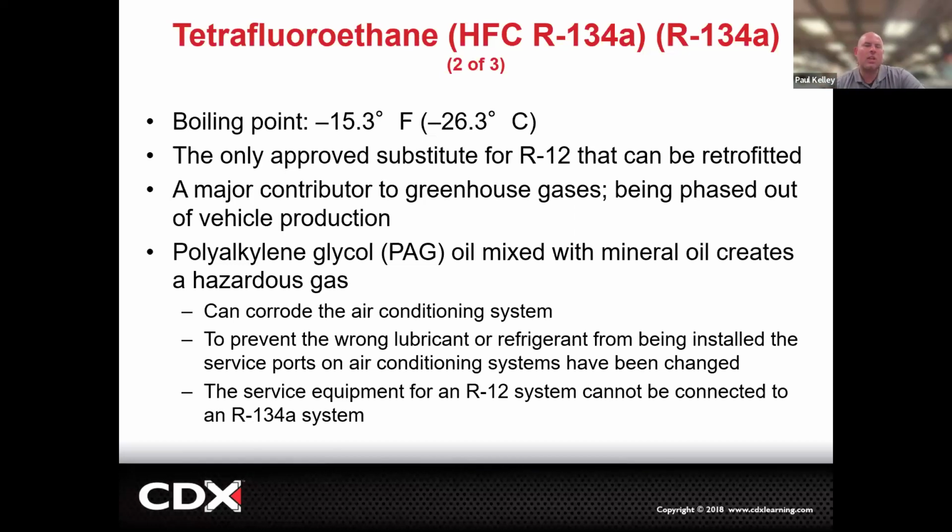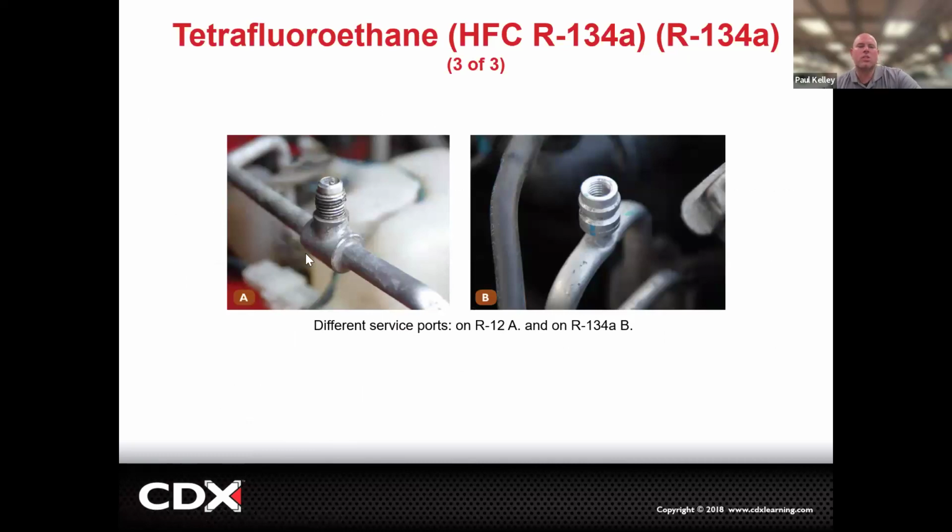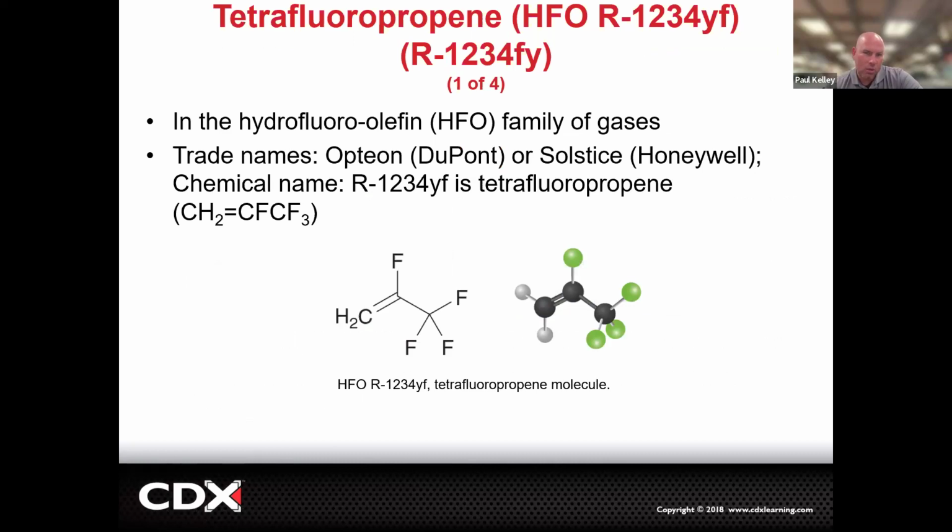And then again, if you have R12 equipment, it can't be connected to R134A system. They change the fittings, so you can't be contaminating each. Cool. So there's your R12, and there's your R134A. R12 is old school, threaded on. R134A is like more of a quick connector. They do have threads inside, but it's more for the valve, for the Schrader valve. All right, and then we got into the YF, right? So the tetrafluoropropene. You can see more complex molecule a little bit.